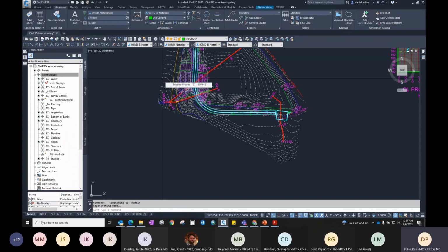That's the two working environments that you work in. Model space is where you work with all the objects in the drawing. By default, you start working in a 3D drawing area called the model space. You begin by deciding whether one unit represents 1 millimeter, centimeter, 1 inch, 1 foot, or whatever unit is most convenient, and then you can draw it at a 1-to-1 scale. So with that being said,